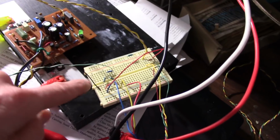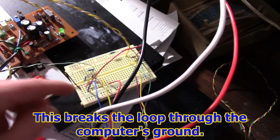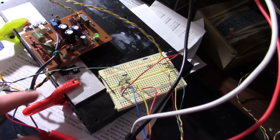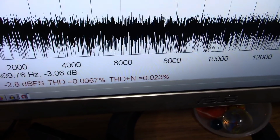So now I disconnected the output ground and brought the input ground lead over. If you measured it with the meter, it'd still be low, but it's the voltage drop across the leads here. So now I'm getting much better.